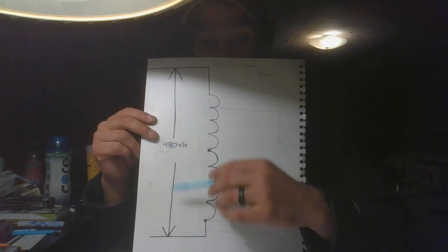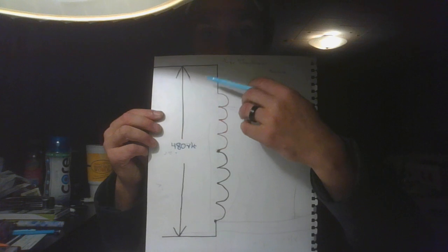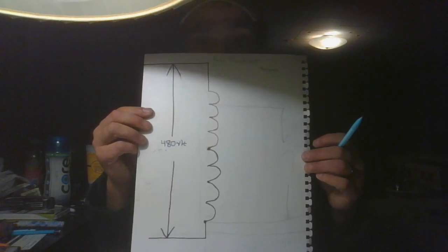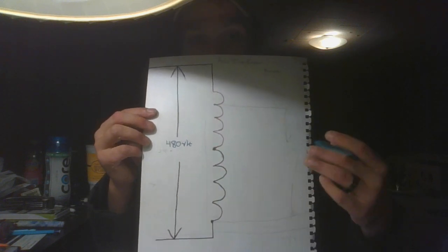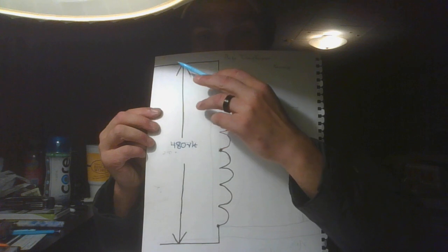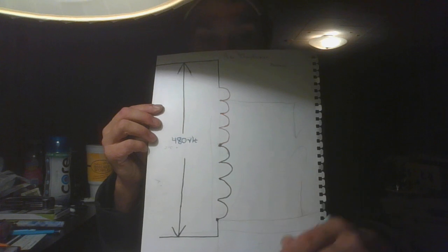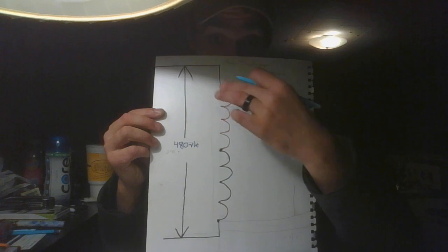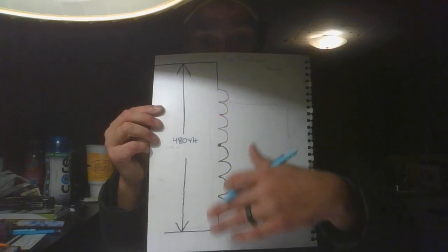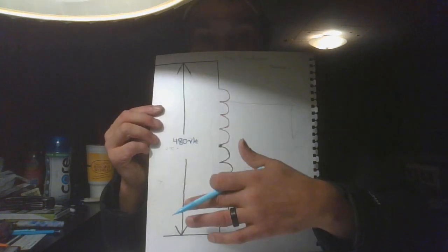If this winding is fed, okay, now let's go over the three scenarios. We're going to say this winding first is fed with the phase-to-phase voltage of a three-phase distribution system. This is a phase-to-phase voltage of 480 volts. In that case, these terminals, these leads, as all you electricians who took the electric motor up know, are terminals 1 and 4, your A-phase winding. Now, back in the generator, these two terminals.